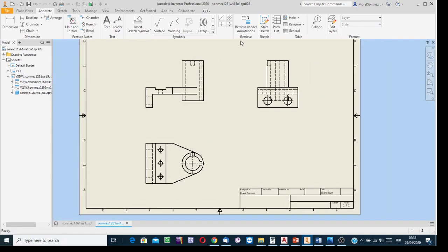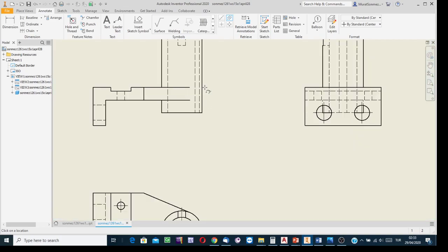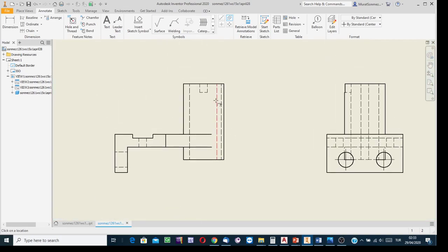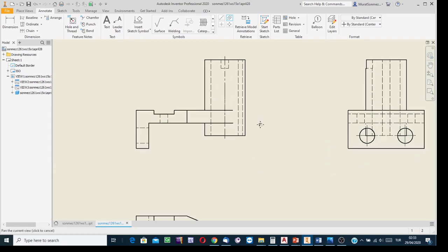And then the others, the longitudinal axis. For the revolved features, on their lateral side views, we need to show the longitudinal axis. A cylinder is a revolved feature, so show the longitudinal axis. If I indicate this surface limit line, I can have the longitudinal axis. One more time, indicate this one and have the extension.